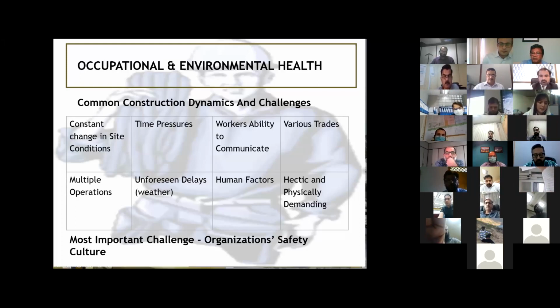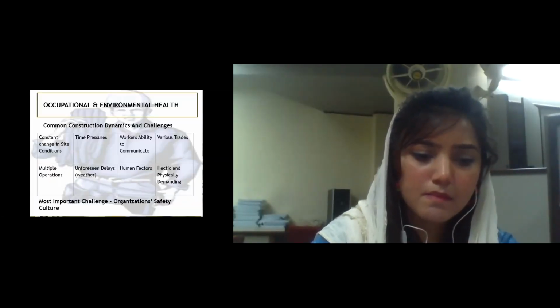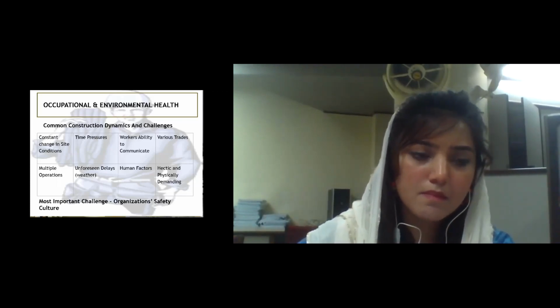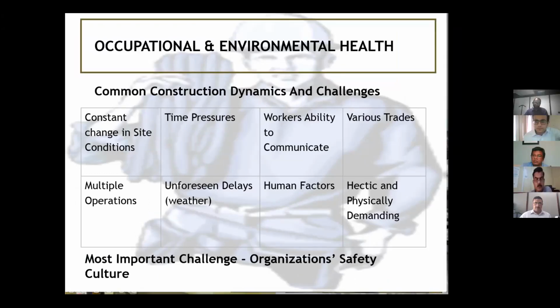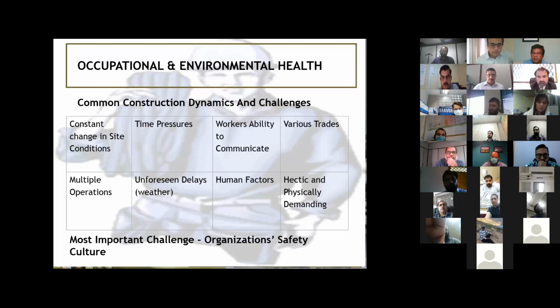Human factors: some people would just ignore or are not ready to follow any procedures. No doubt, wearing respirators, hard hats, shoes, those white Tyvek suits is hectic. For the last 4 months, every one of us has been using those masks, and you would have felt how difficult it is to breathe. After maybe 15 minutes, it's uneasy. Those masks are relatively easier because you don't have any filters, it's just air going in. But with these respirators that I showed you, it is really very difficult to breathe. So the workers who are using those usually have a break after every 3 or 4 hours.